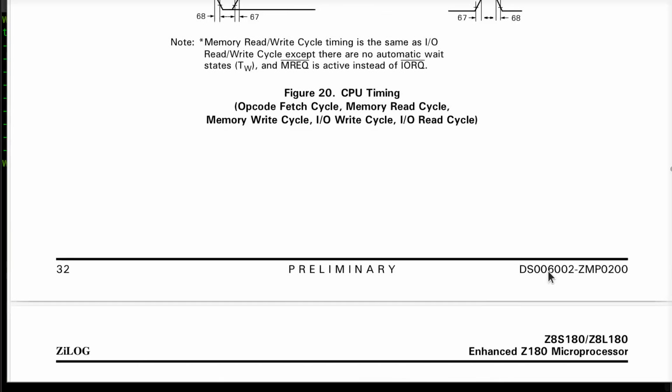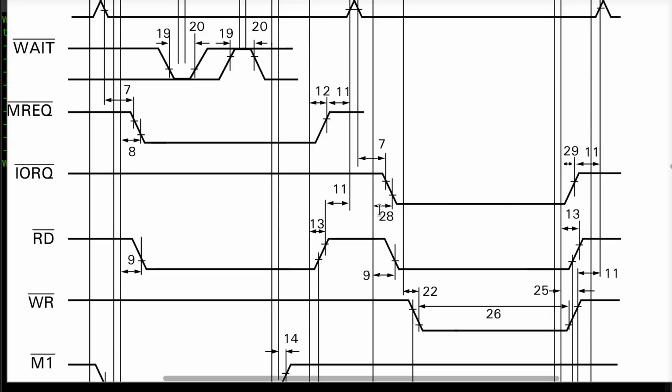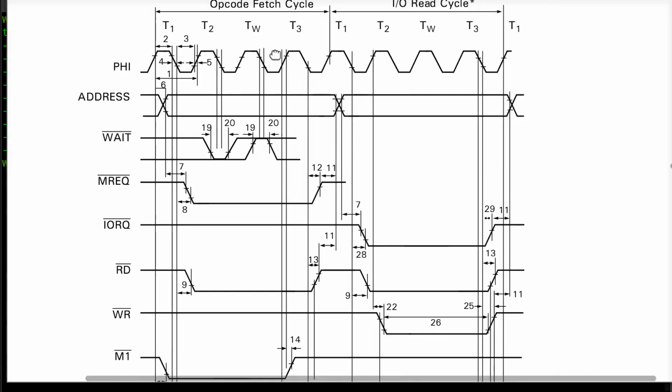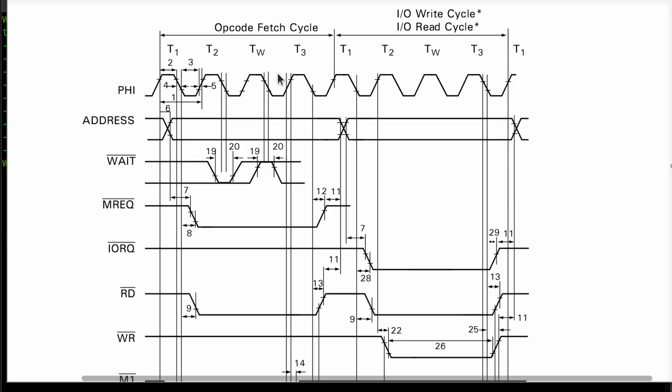So what that means, in the worst case scenario, is that this wait state is optional, and I have it disabled on this processor, if you're not really following the channel. If you are, the memory, I turned off the wait states. You cannot turn off a wait state during an I/O cycle on this particular processor. This will all become a little more important as we go, because I have to pick which edge I want to use when I'm transferring data into or out of the CPU.